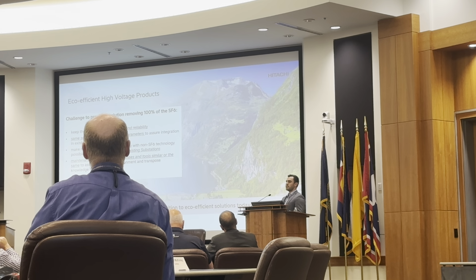And then lastly, operation and maintenance, especially for a maintenance crew in the field. It's the same exact processing tools. As a matter of fact, there's service spare parts that you can take from the SF6 and use on the SF6-free technology. So nothing changes. Using the same cameras, the same monitoring systems, the same partial discharge, and the same maintenance practices.